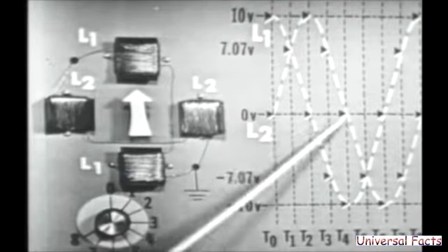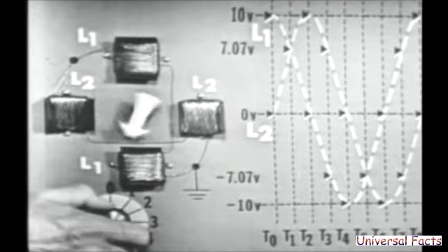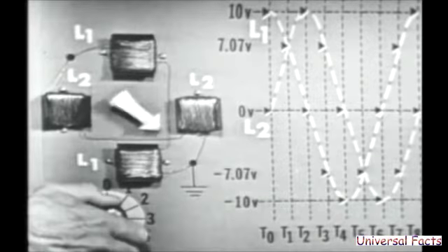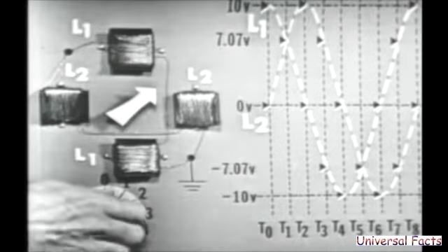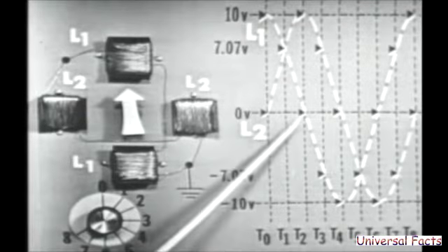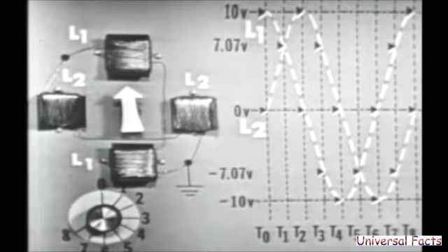Okay. A rotating magnetic field is achieved by applying out-of-phase voltages to the stator or the field windings, which we represented on this demonstrator. Now, you should point out, Bob, that the most effective phase difference to use is 90 degrees, as we did. Right. It'll work at other phase differences. In fact, any phase difference other than 0 or 180 will give you a rotating magnetic field, but as you said, the most efficient one is 90 degrees phase difference, and that's the one that's probably most commonly used. Right, now I'll take item 4.